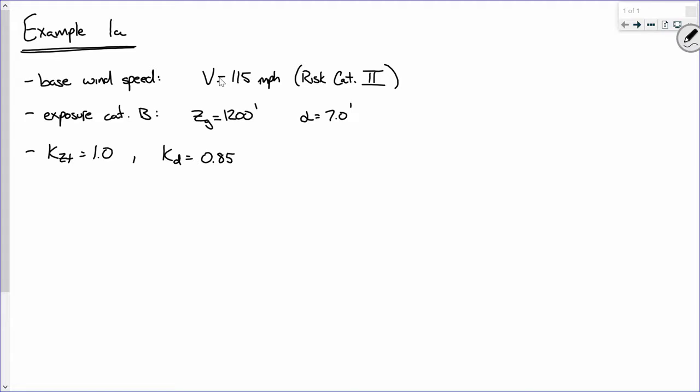Okay. So what we have to do in order to do this is we calculate a base wind pressure at each story of the building. So we would have to do this calculation 4 times, one for each story. So because you're having to do this calculation over and over and over again, it's starting to sound like a nice Excel calculation, right? Nice repeated calc. We're going to do one of them by hand, and then I'll show you the Excel file that does them all. So let's consider the 4th story, and I just sort of picked the 4th story.